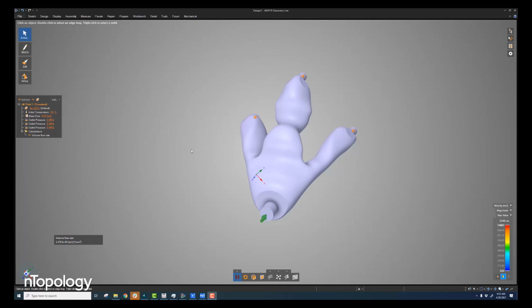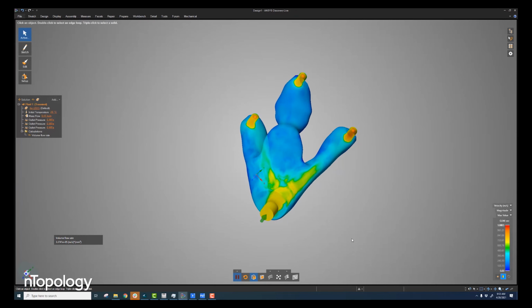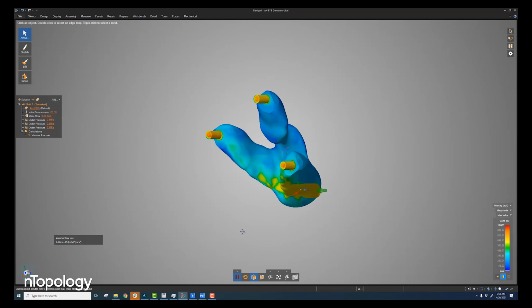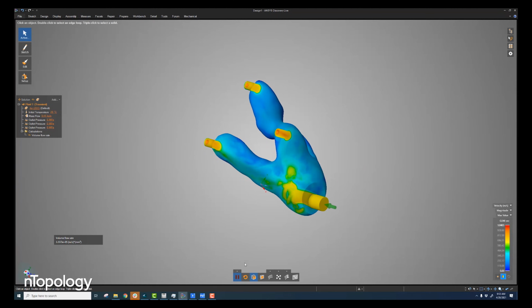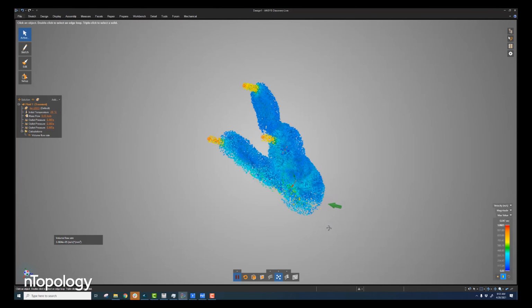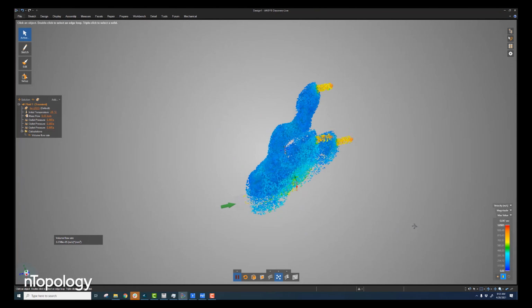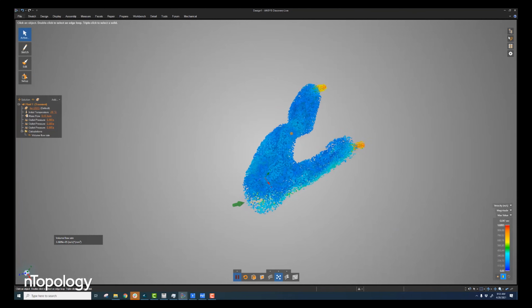That could be the fluid flow paths, right? Here's an example of a manifold where you have 3 outputs and 1 input, but you want to maintain constant pressure. In this case, we're taking the fluid flow path results directly from Fluent, from ANSYS, and optimizing these flow paths so that we have the same pressure on all of the outputs.